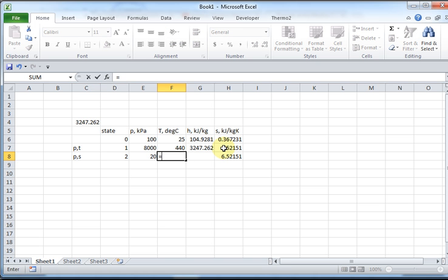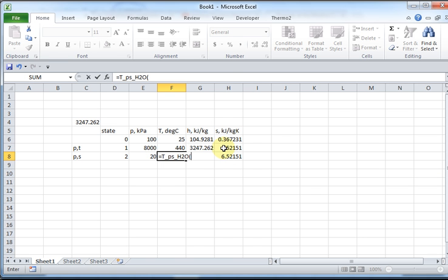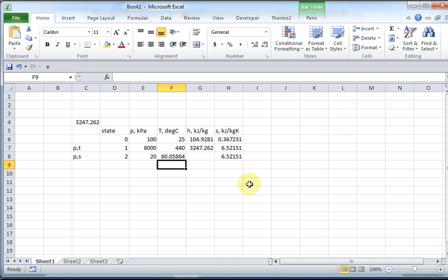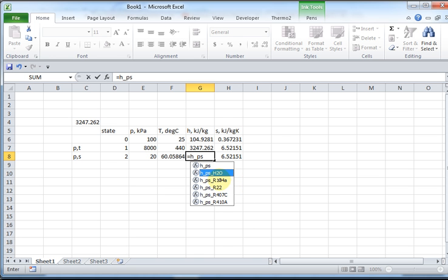It's a little reminder for myself, a little note I put typically right there. And then I say, oh, I need the temperature as a function of pressure, entropy for steam, right? Then I click this cell for the pressure, and I put a comma. Then I click that cell, close paren, return. There you go. Notice this H is a function of pressure, entropy for that steam, pressure, comma. Now, how many people know how to do this? I just click below and then tuck it in. It's not nice, is it? I don't know why. It's so hard to click the cell. The formula equation's covering up the cell I want to insert.